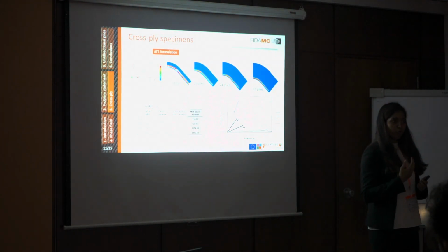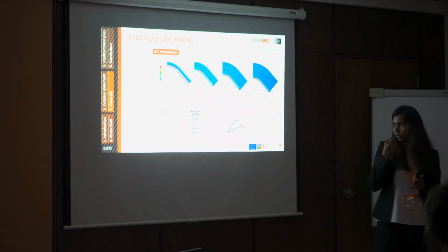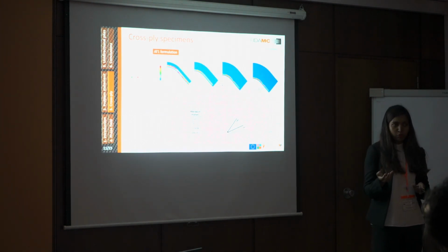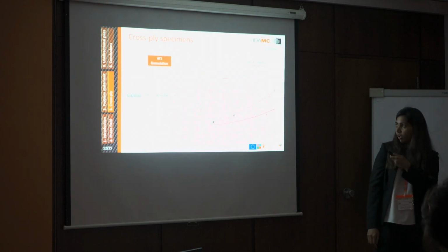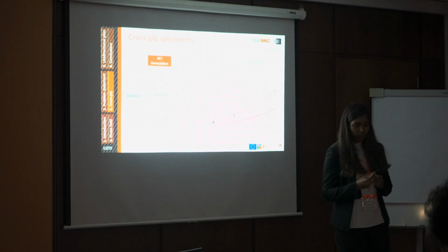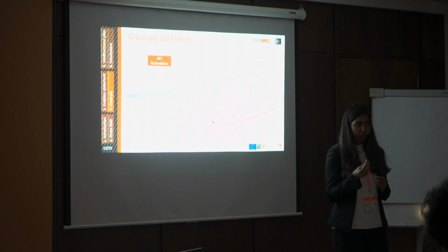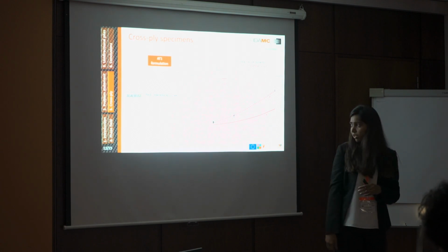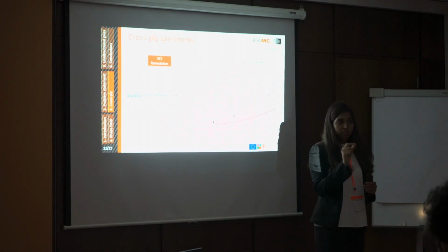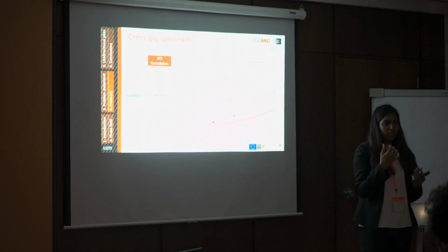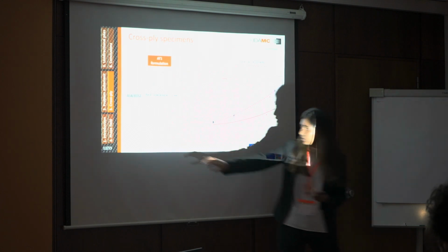But our main focus is to determine the intralaminar failure phenomenon, which is the damage initiation. We have analytical calculations for determining the intralaminar failure for the experimental data, and from the numerical model, we took the first non-zero phase field value as our intralaminar failure.